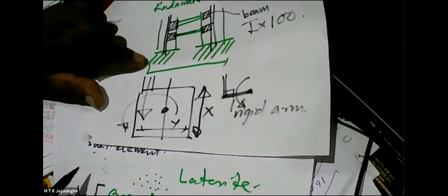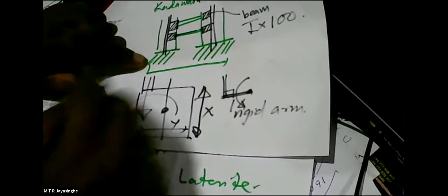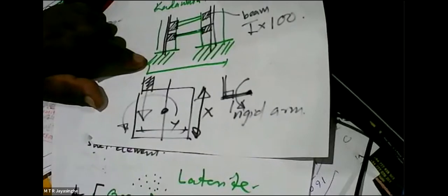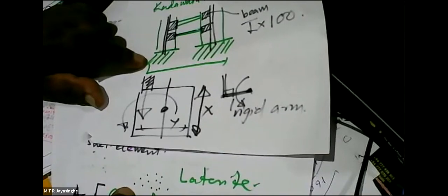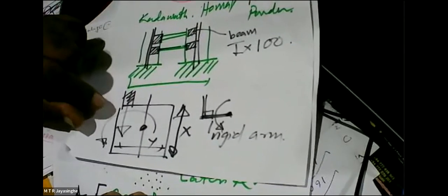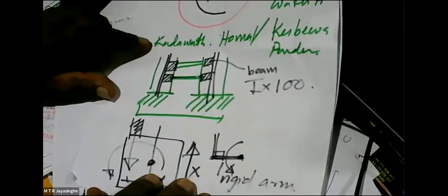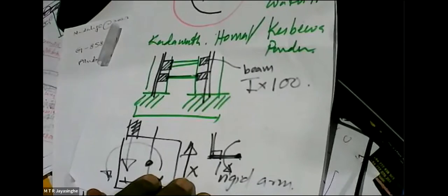And sometimes we deliberately make them wider to ensure some of these walls that are at odd locations can be brought onto the beam rather than putting in various additional members, because every additional member means some additional work at the site. So you have to always ensure that your models are accurate. That's why I taught this rigid arm concept, because in SAP 2000 you don't need it, but here you need it because you are dealing with the rigid arm concept.